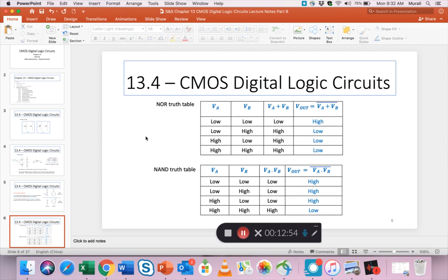It's a truth table, right? The one thing I wanted to tell you is, as we study this chapter, rather than talk about the OR function and the AND function, we talk more naturally about the NOR function and the NAND function, which is the opposite, the complement of OR and AND. Once you have a NOR, you can always convert it to an OR. All you have to do is put it through another inverter, and then you get the opposite.